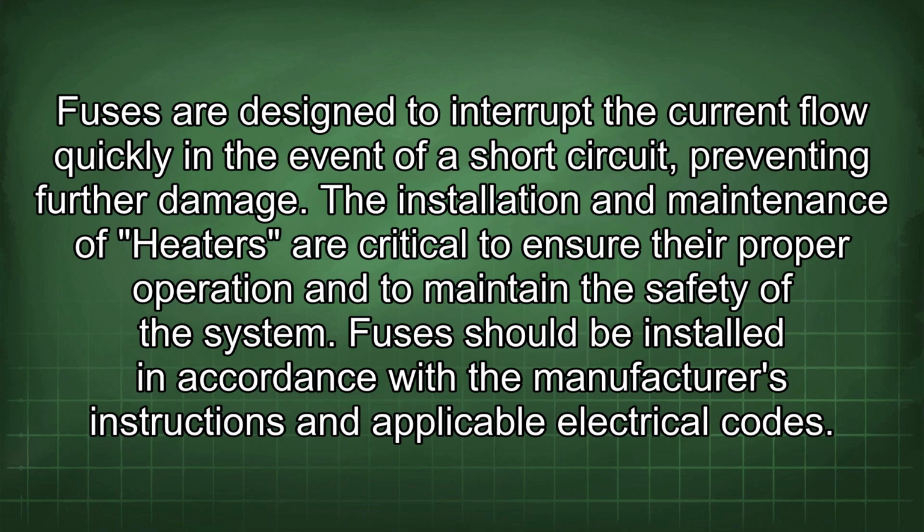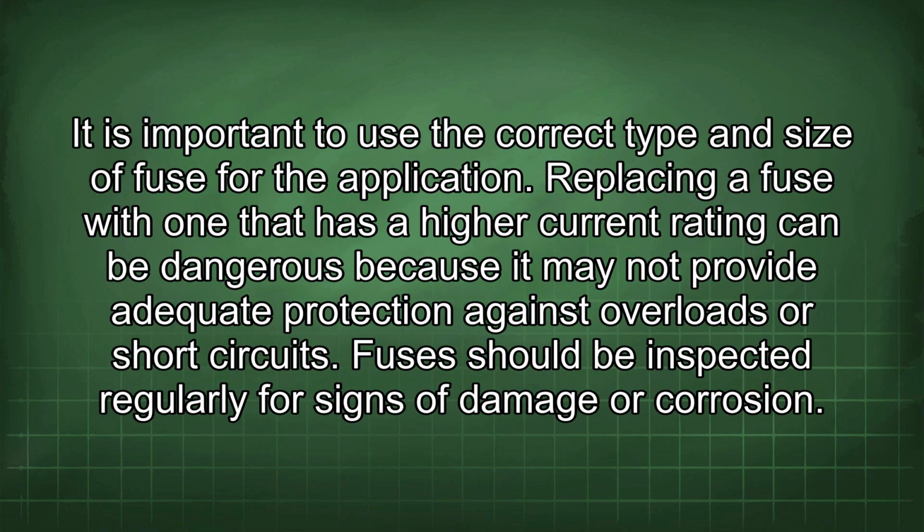Fuses should be installed in accordance with the manufacturer's instructions and applicable electrical codes. It is important to use the correct type and size of fuse for the application. Replacing a fuse with one that has a high current rating can be dangerous because it may not provide adequate protection against overloads or short circuits.